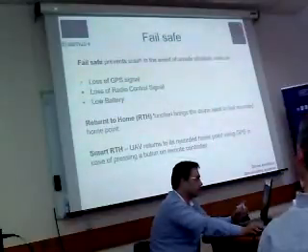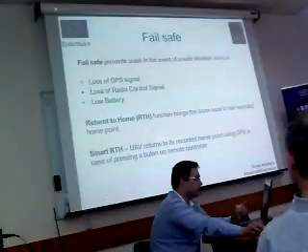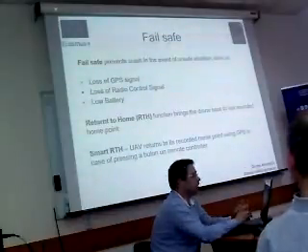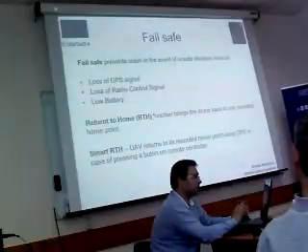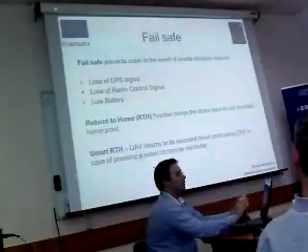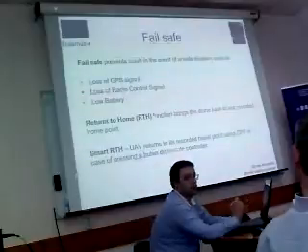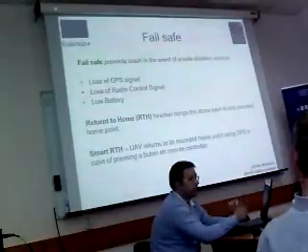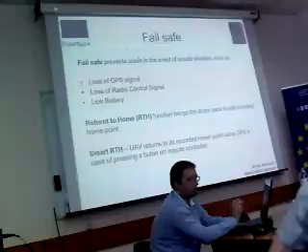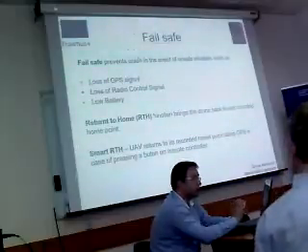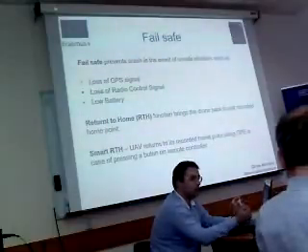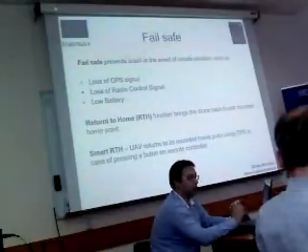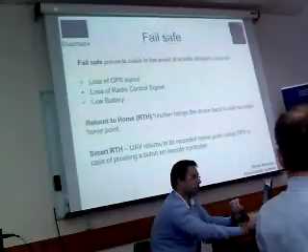In the third scenario, low battery, the failsafe is triggered when the intelligent battery drains to a level that may cause problems in returning the aircraft. So when the battery level reaches the minimum level required for the aircraft to return to home, the failsafe system will be activated and the aircraft will automatically go home. If the controller determines that there is not enough power left to get the drone all the way back to the home point, it will automatically land the drone rather than have it just fall out of the sky.